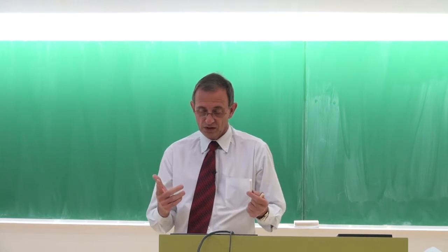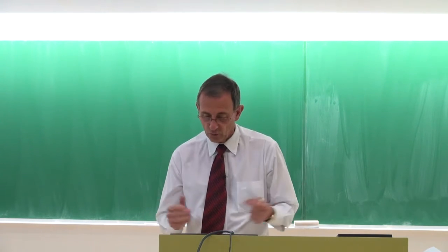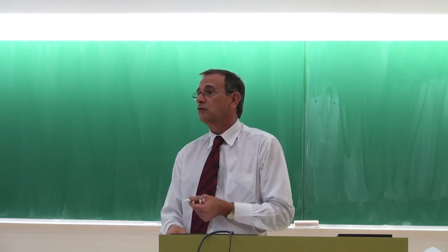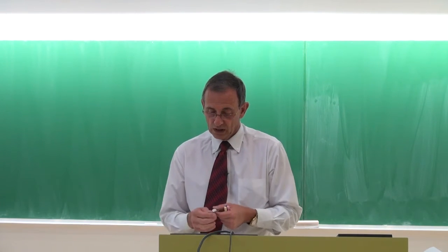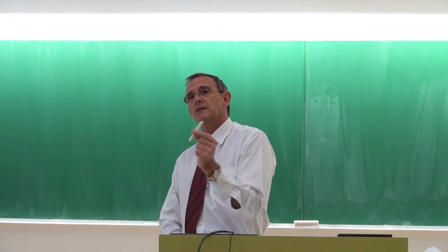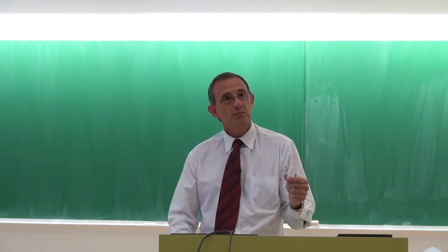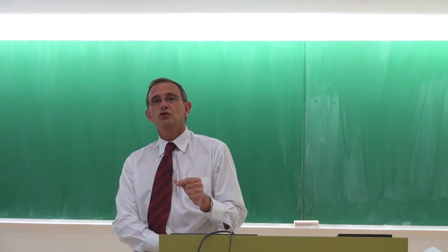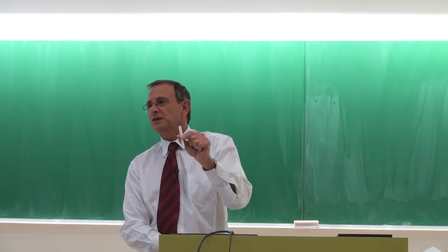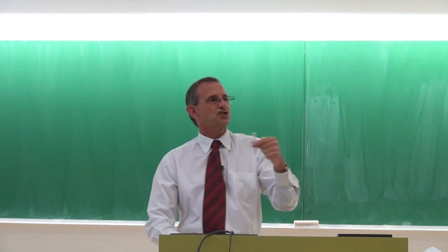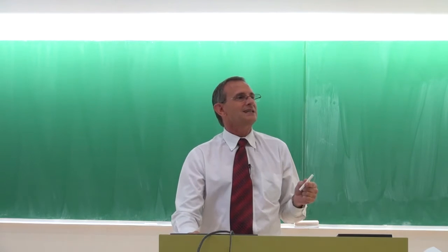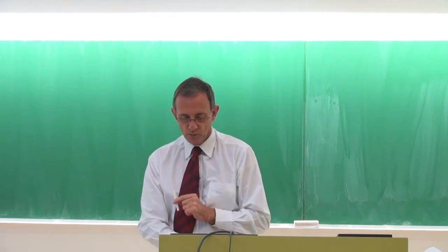So we have started with an introduction, of course, with this chapter, in which we have looked at where internal forced convection is important. I've shown to you how the velocity distribution and the thermal layers develop, and specifically why we have to get the average mean temperature, and that we cannot just do an integration of the temperatures. We have to take into consideration the velocity at every point, or the mass flow, because that is what's transferring the energy. So getting the Tm value, the mean value, is very important.